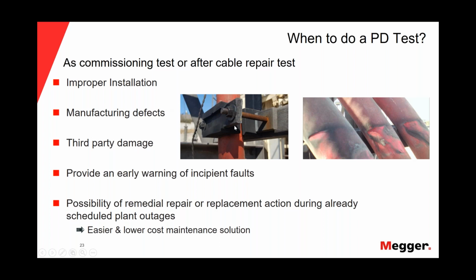As you can see in these pictures, the person that fixed the cable in the holder exceeded the torque, and for this reason they deformed the insulation of the cables. So for that kind of problem, partial discharge will help us. Partial discharge will provide an early warning of incipient faults, and we will have the possibility of remedial repair or replacement action during an already scheduled plant outage.